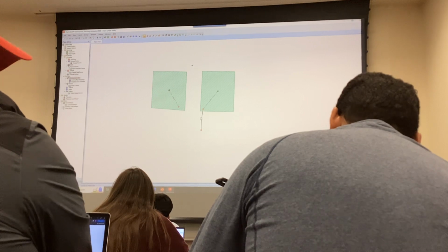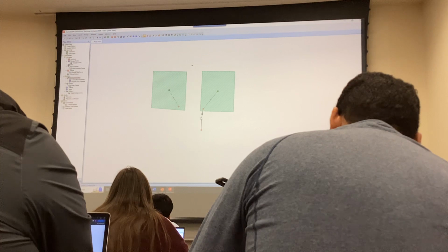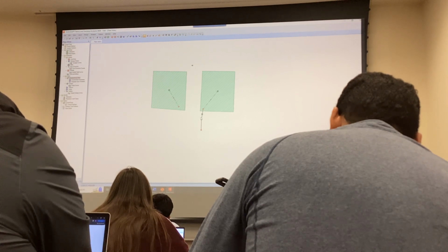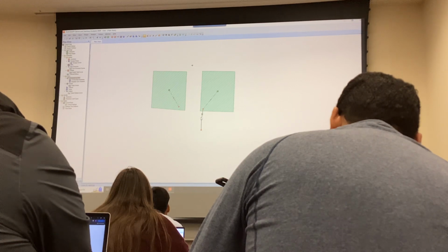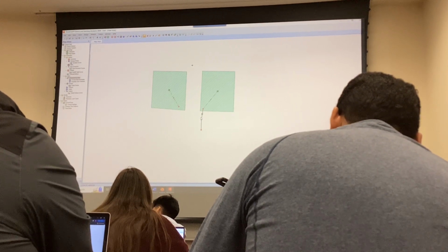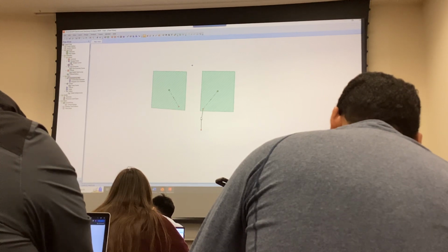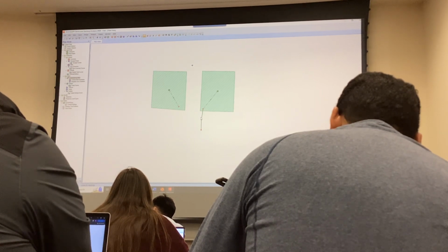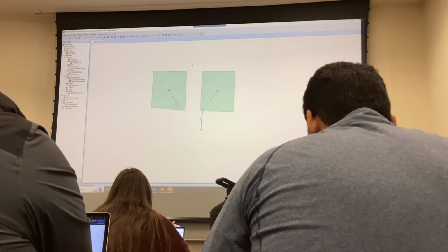Right? So in this case, we only learned the sharp-crested weir here and the orifice. So I can say that at a certain elevation, I'm going to put my orifice, and at the top, I'm going to put my weir. So you can have an initial concept of what you want your outlet structure to look like. Okay? And then you can start also by saying that this has a centerline associated to it, and this has a certain elevation associated to it. So by doing this, you have a great starting point. Okay? And I'll tell you why.